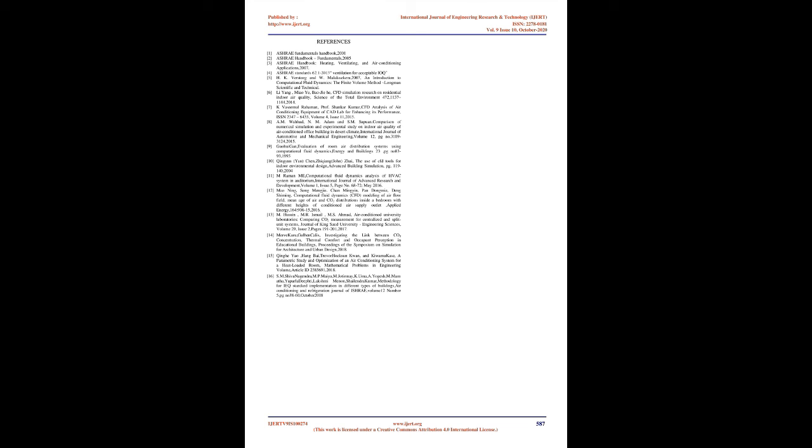8 Conclusion. This study presents a comparison between the experimental data collected and the numerical data simulated. Numerical results are in close approximation with the experimental one. Computational fluid dynamics approach has predicted the air temperature and the flow pattern in the laboratory. The conclusions are as follows. Cooling load calculation shows a grand total heat of 67,863 BTU/HR, i.e. 5.7 tons of refrigeration is required for the laboratory. In this there is a larger share of occupant load and appliance load.